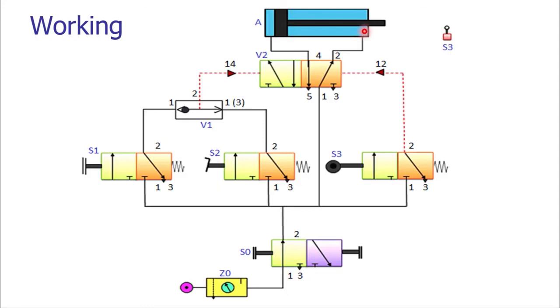As the pressurized fluid has been applied on the other side, the piston rod will be displaced from right to left. In this way the retraction or the contraction of the piston cylinder arrangement will be carried out. Thus we have seen how this variety of pneumatic elements are helping to have an efficient and systematic operation of the pneumatic based circuitry for the desired application. In this case it is displacing the components from the magazine.